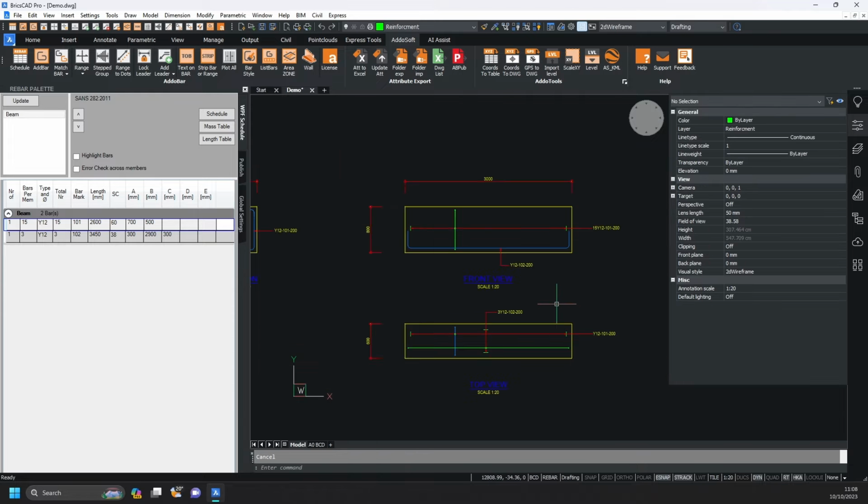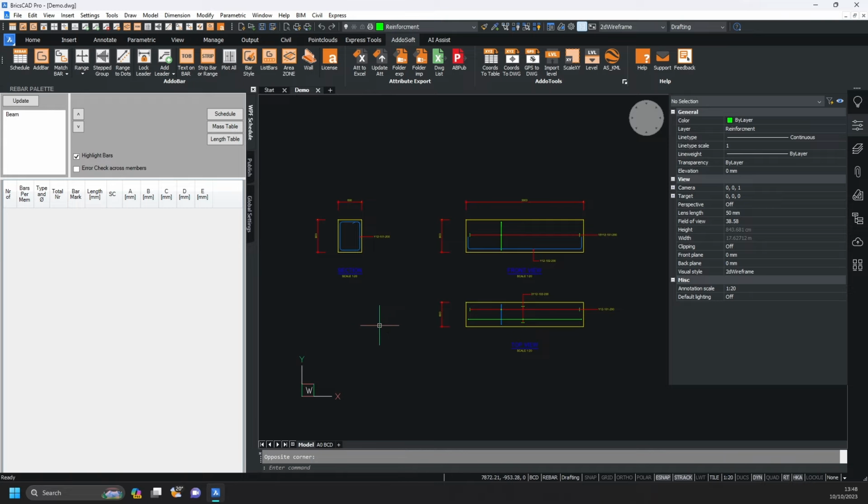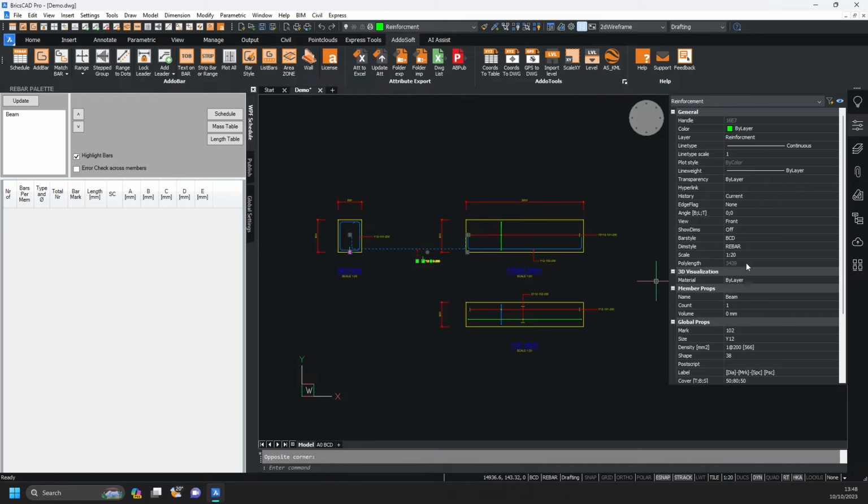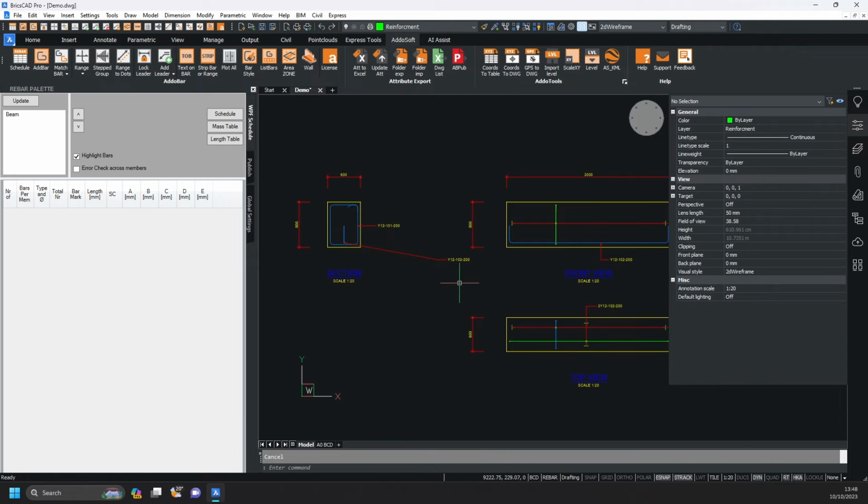Now we can add the shapecode 38 to the section view. Copy the bar in the front view to the section. We can then change the view to side. Just a note on the leader. It will be automatically removed and re-added when we call the range command, so we don't have to worry about the current placement of it. Click on the range command. Now we can select the bar we want to range. Pick a range start point and a range end point. Then choose where the leader goes, and after placing the leader, press Escape to end the command.